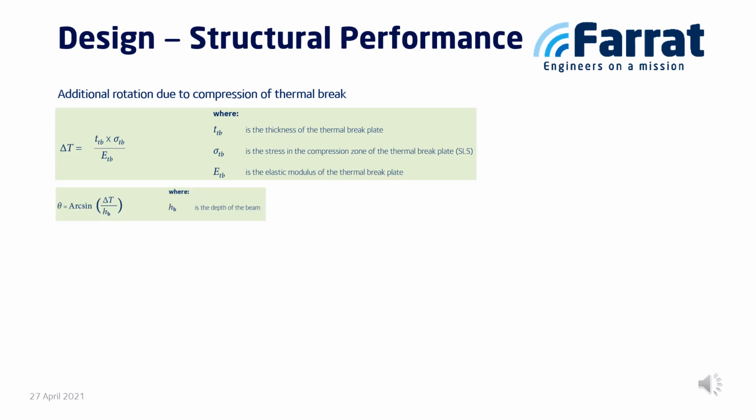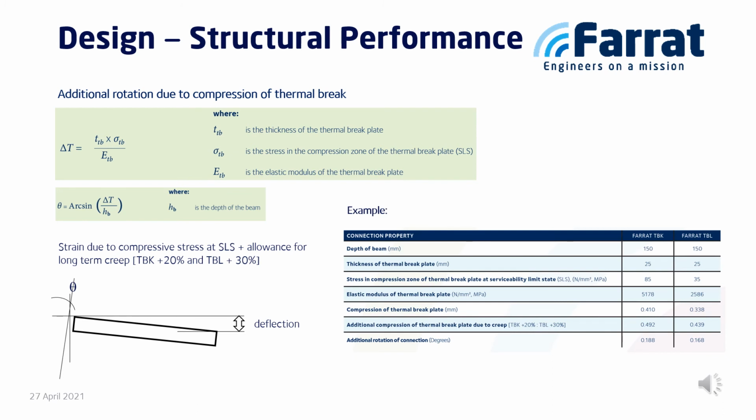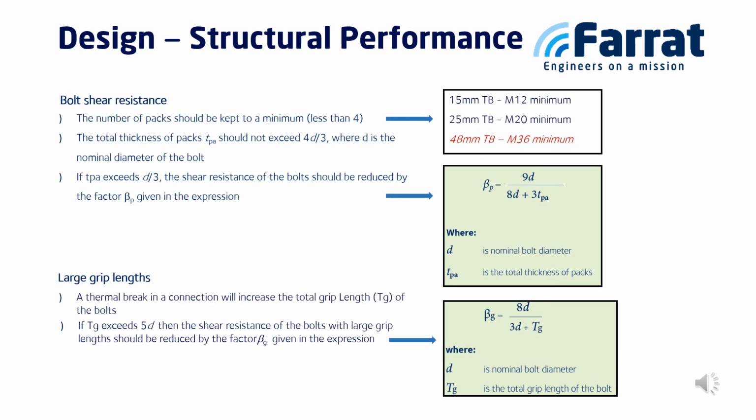All material-material connections have the potential to rotate under load. Note should always be taken of a chosen structural thermal break to resist these loads and not to compromise the short and long term performance of a connection with undue flexibility or excess creep. Structural thermal breaks typically limit the extent of their load transmittance for design purposes to the transferal of compression loads. The main connection elements typically deal with shear loads, and notice should be taken of the effective connection's length in relation to the thickness of the structural thermal break specified. 25 mm thickness would typically be the optimum without having to consider increasing the size of the bolt.